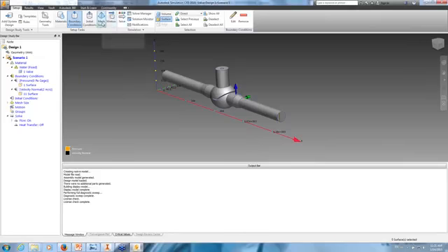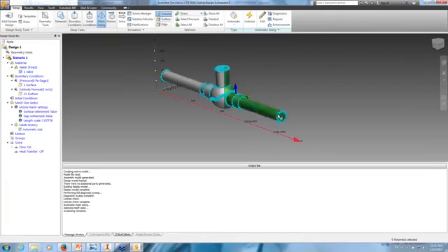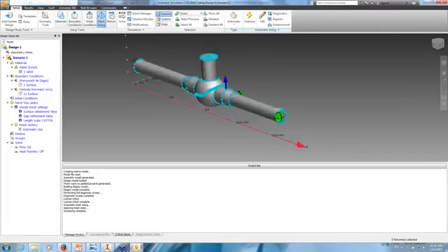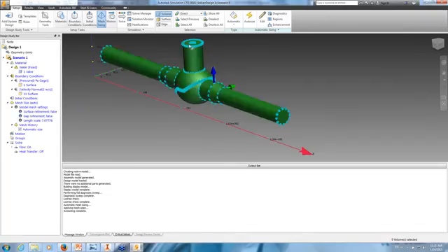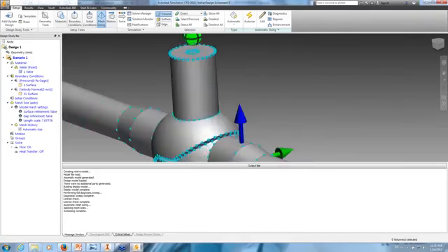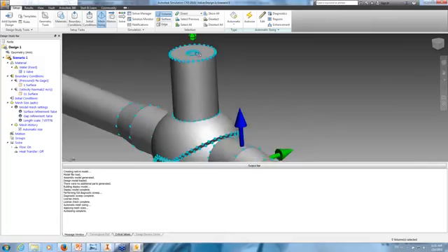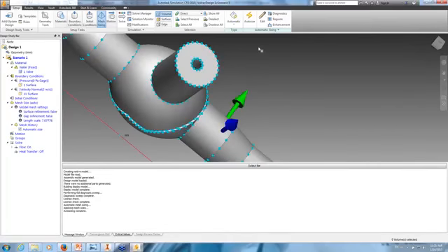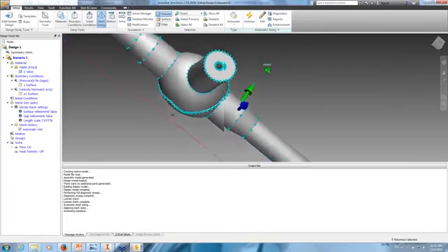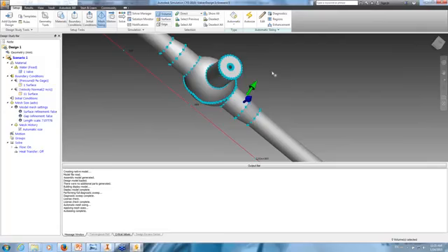Next, I'm going to go to the mesh sizing and click on auto size. The options here are either automatic or manual. The easiest way to do it is automatic auto size. These blue dots here give you an indication of how dense or coarse the mesh is. Of course, if you have finer features in the model, you would get more dots to be able to capture that. And I'm going to just leave that as the default. We'll go into it in a later example. I'll just show a couple of things you can do with the mesh, but not in this example.